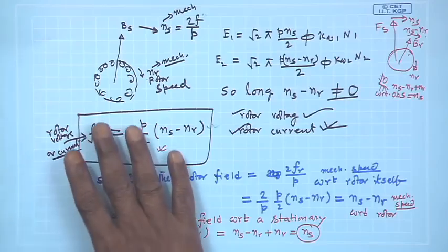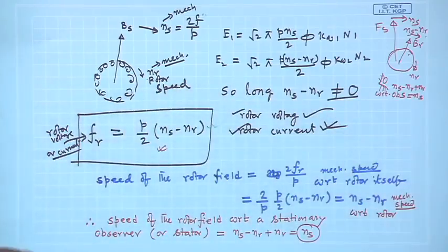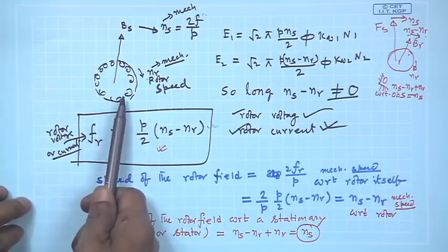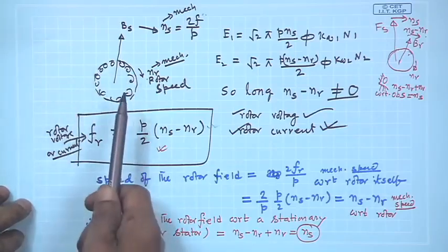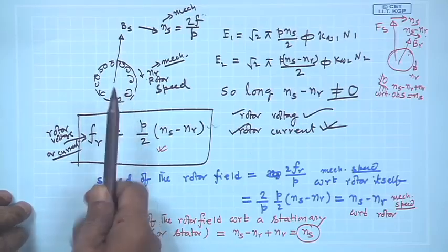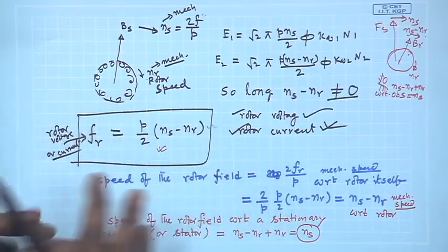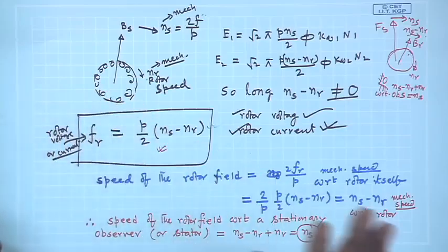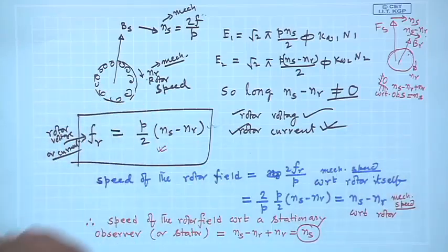Therefore, the rotor will pick up speed, if the rotor is allowed to move, no locking. The rotor is allowed to move and the rotor circuit is closed, then only can rotor current exist and then only the question of movement comes in, and this is how speed grows.